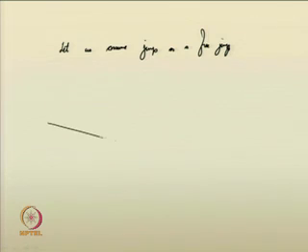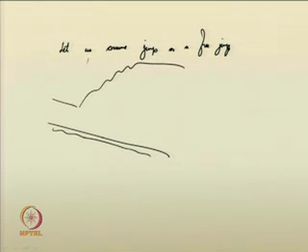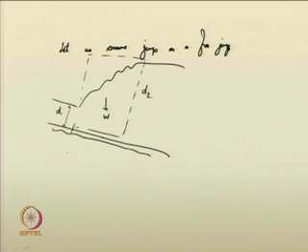So, if we have a free jump, if I draw the control section for the jump, let this be the depth d1, let this be the depth d2. Okay. So, you have the weight of water W acting like this. So, in this control volume, we can incorporate the momentum transport equation.